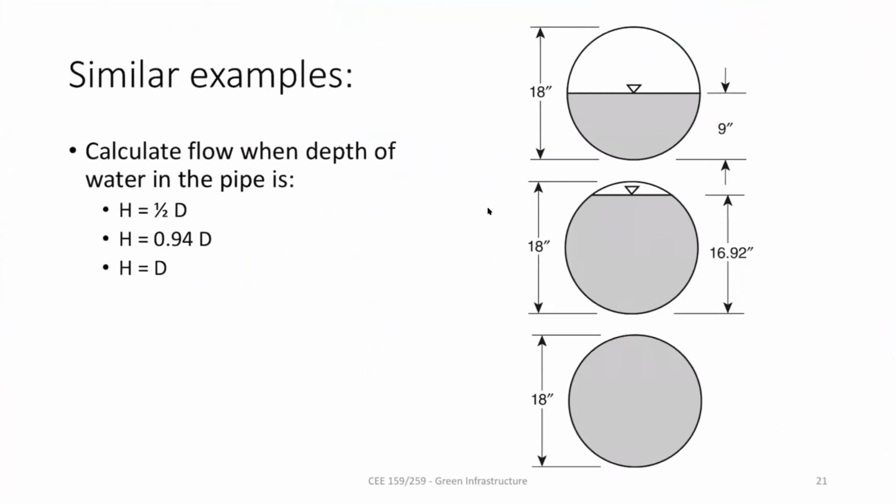This is another reason why, a lot of times, for storm water, people create this kind of a barrier to direct storm flow in certain directions. That depends on multiple factors, not just the pressure, but also the soil seepage rate and the geotechnical properties of the soil. But here, we're not going into details about that. You just understand that this design takes into account the pressure exerted by the storm water.